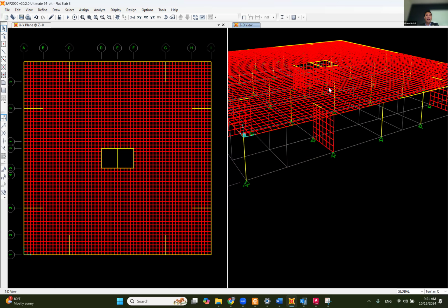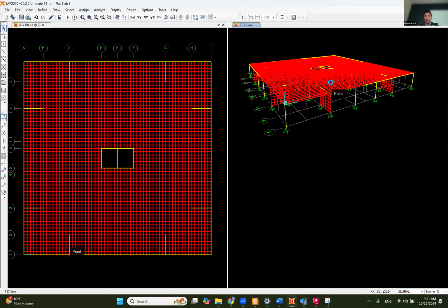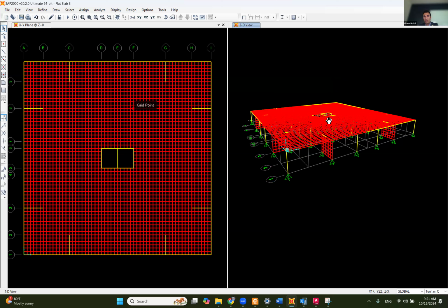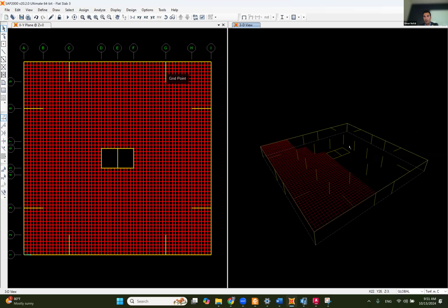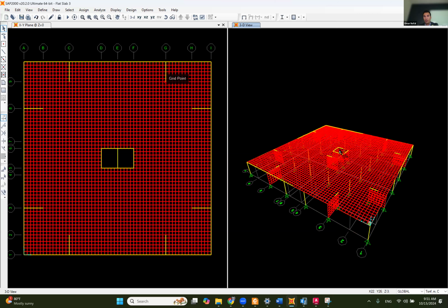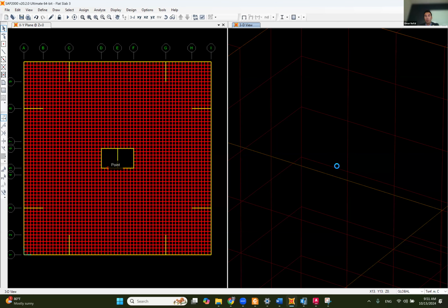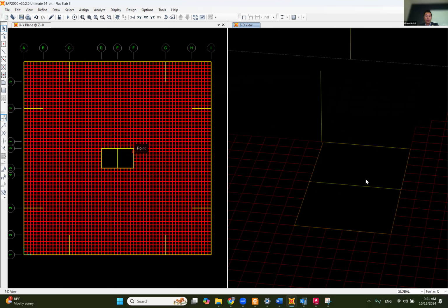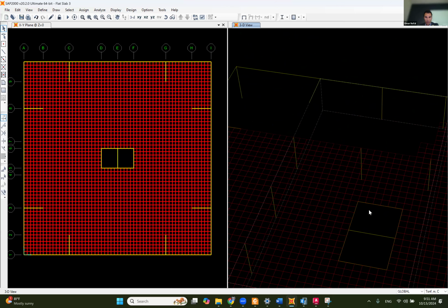All right, so here all the wall sections are divided except one wall that hasn't been divided yet. The model is a little bit heavy because we have lots of meshes here. I want you to look at this wall in the middle. This wall is divided just in one direction, not in the 2 direction. Why? Because there weren't any joints from the slab connected to this wall. Look, the one here in the middle.